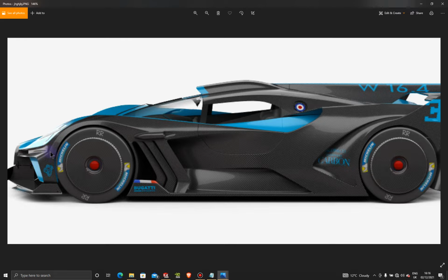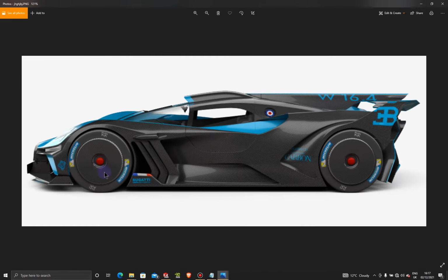And then the second one is going to be from this point here all the way here, with a break and an angle. Up here it will drop towards the center, and then here it drops a little bit, drafting towards the center as well. But you will see when we get to that one. So let's create this first 3D sketch and sketch projection first.